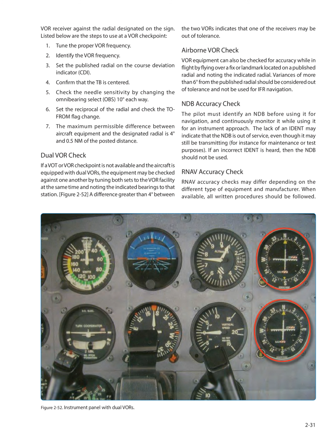NDB accuracy check. A pilot must identify an NDB before using it for navigation, and continuously monitor it while using it for an instrument approach. The lack of an IDENT may indicate that the NDB is out of service, even though it may still be transmitting, for instance for maintenance or test purposes. If an incorrect IDENT is heard, then the NDB should not be used.